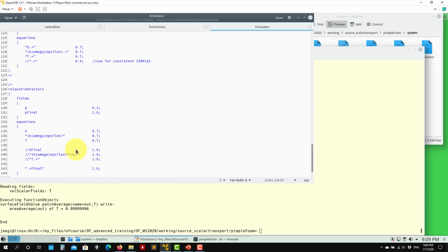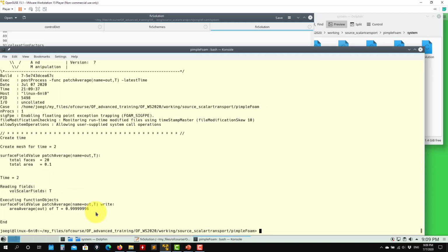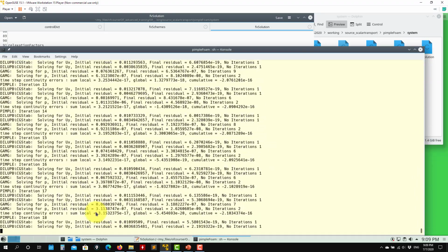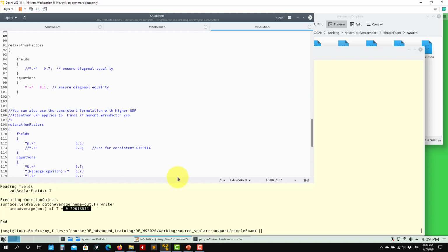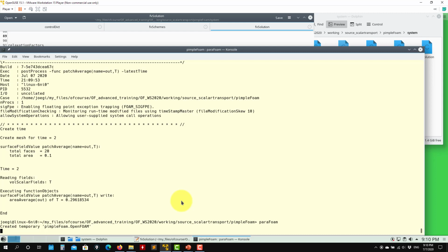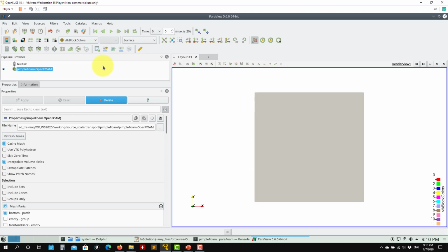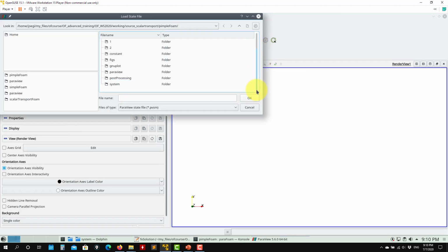And again, remember that this will have a strong influence. So if I go here and put 0.1, I will add more stability to my solution, but I might not reach that final state. And see here that now, by putting a too low under-relaxation, you are losing your time accuracy. The problem is working, you have a healthy stability. Okay, we know that increasing the under-relaxation will improve your stability, but you are losing time accuracy.